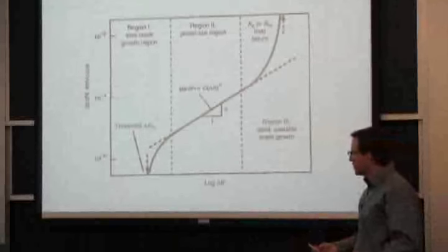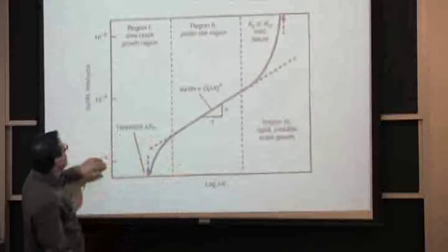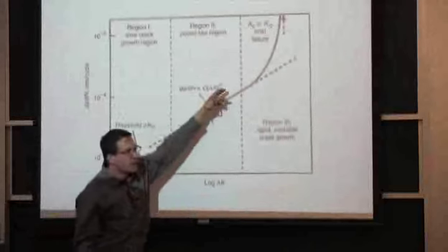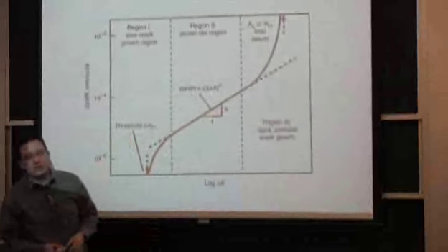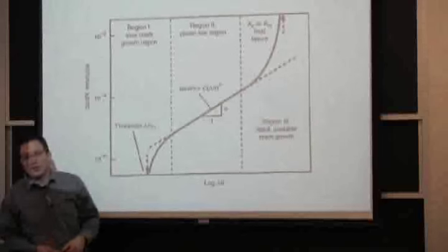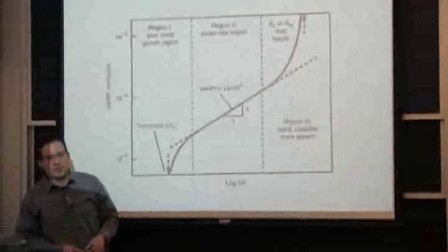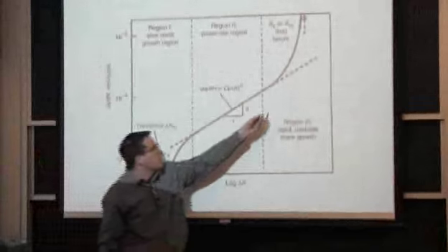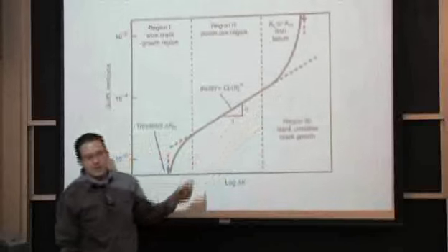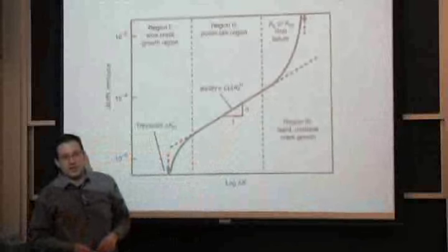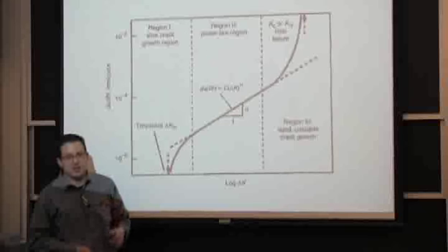When you think of it in terms of cycles, if from when you start cracking till you reach the acceleration regime you went up by 2 to 500 times your crack growth rate, well, it can't be that the very last bit's going to make a difference. So most of the time, when you start losing the linearity in this curve, we'll call it a day. That's as much resistance as you're going to get out of the material as far as life assessment approach.